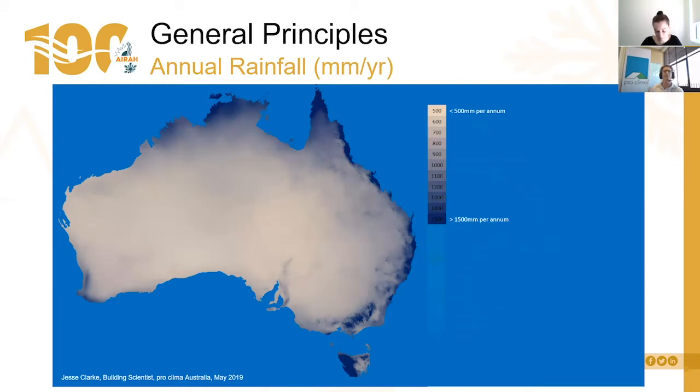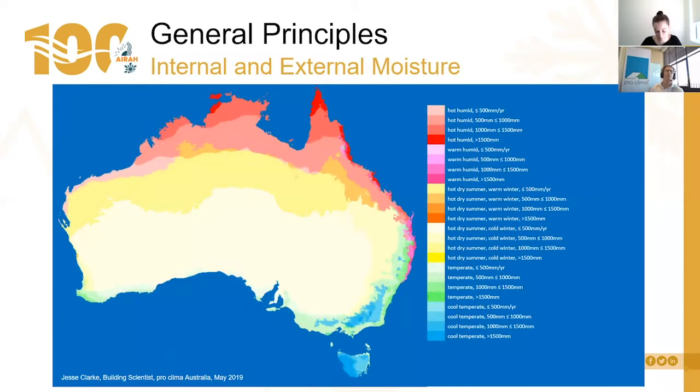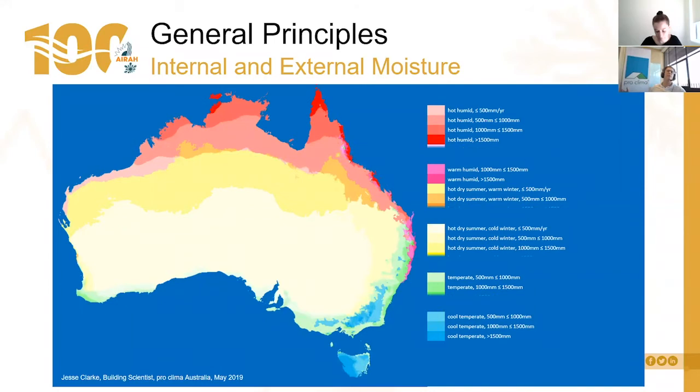Next, please. So overlaying those two things, you end up with two sources of moisture. Moisture outside the building that might get into the structure, and moisture from inside the building generated by occupants and behaviours, in the form of humidity in the air. There is also external humidity in the tropics. Those two sources of moisture, exterior and interior, need to be managed within the construction envelope, and we can now do that.